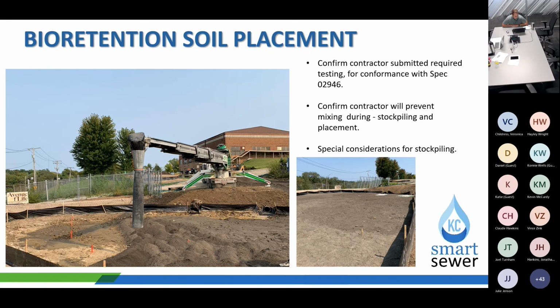It should be placed in lifts, so it specifies 6-inch lifts. As you can see from the photo, kind of placing it like concrete, 6-inch lifts using the telebelt, working your way down the basin. And then also BMP soil should not have any heavy equipment tracked on it as well. So everything should be done and placed from outside the basin.